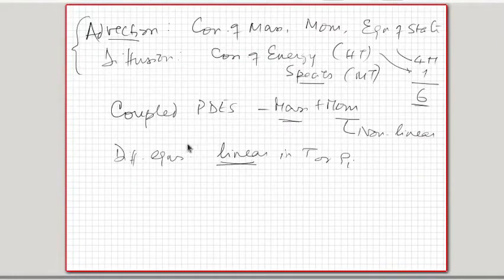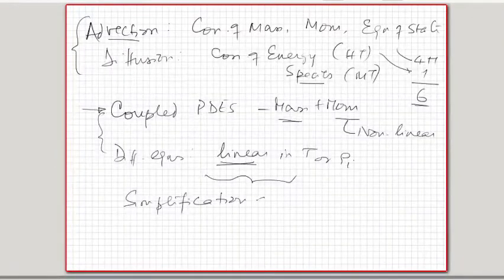Okay, but the velocity components that are required in order to quantify the advection come from the coupled nonlinear partial differential equations, and therefore the overall system of equations becomes coupled partial differential equations which contain nonlinear equations, right? So the system of equations is actually quite difficult to solve analytically, and therefore quite frequently the method in convective heat transfer is to simplify many of these equations. So various degrees of simplification of the governing equations become necessary when we deal with the governing equations of convective heat mass transfer.